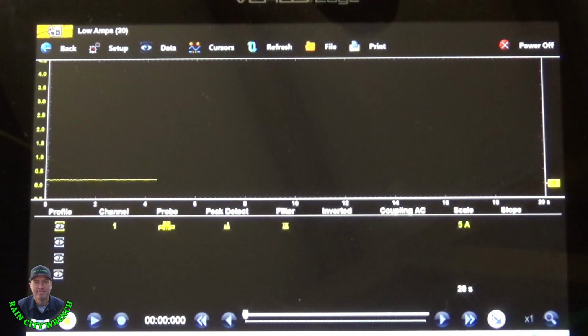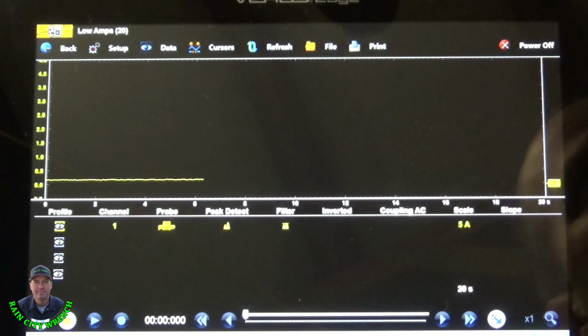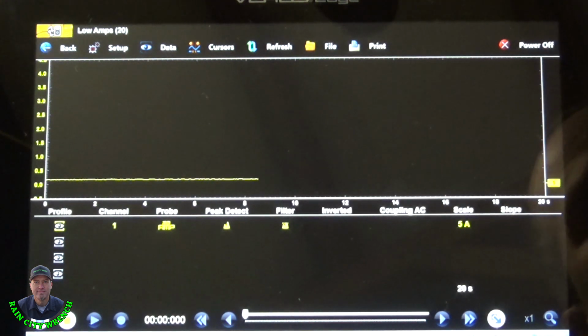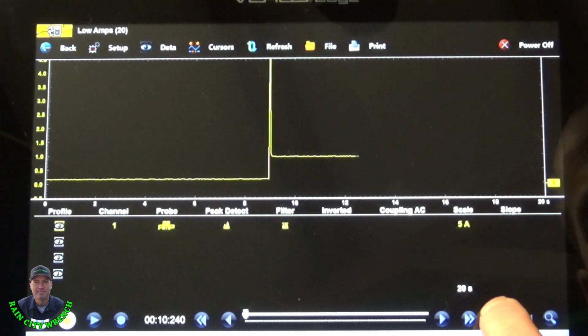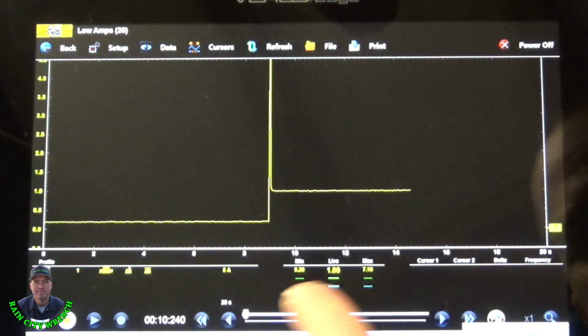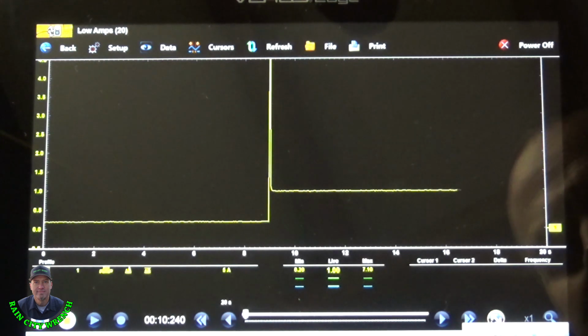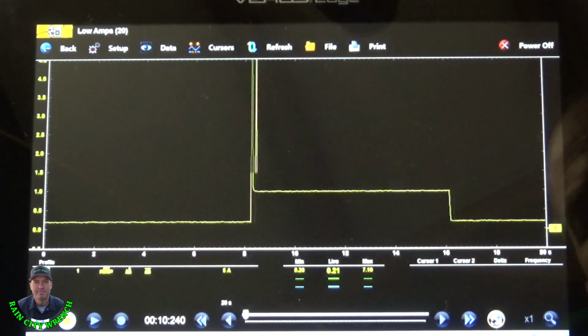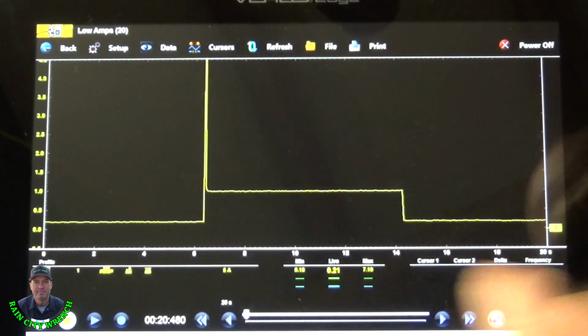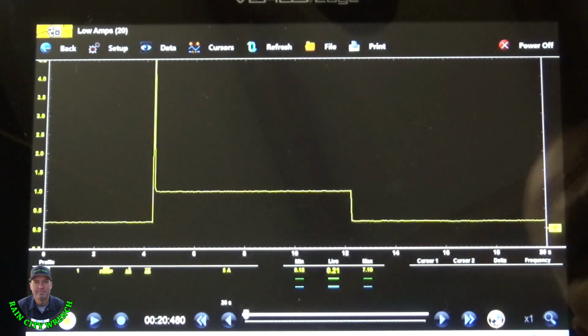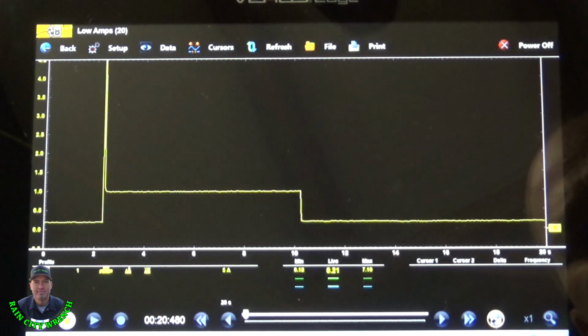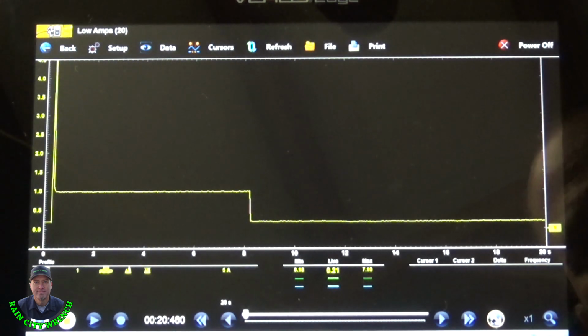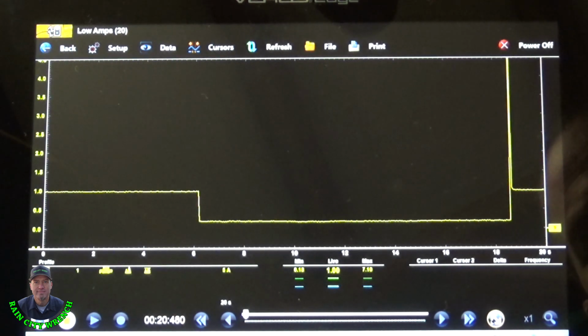And then I'm gonna plug my under hood light back in, see what that pulls. So now we're up to 1 amp. I'm unplugging it back down to that 200 milliamp or 210. So this hood lamp's taking about 800 milliamps. Let me plug it back in. There, it's back on.